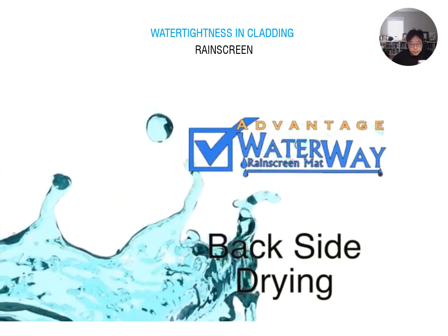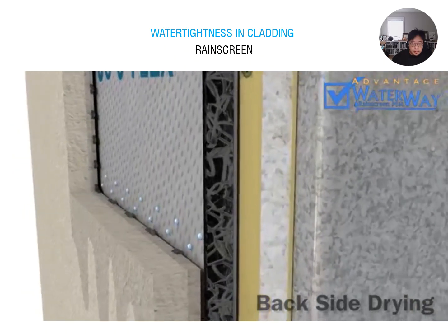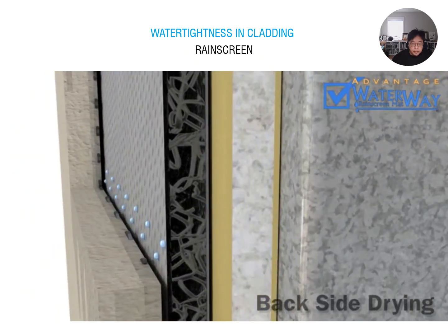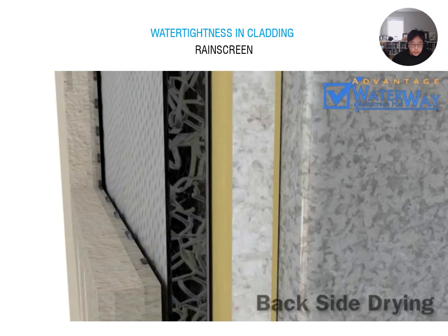Advantage 5. Backside drying. The perm rating of our fabric exceeds 200. This means it promotes the backside drying of your exterior materials. Moisture in the facade is allowed to evaporate through the filter fabric, allowing the wall to dry from the inside.